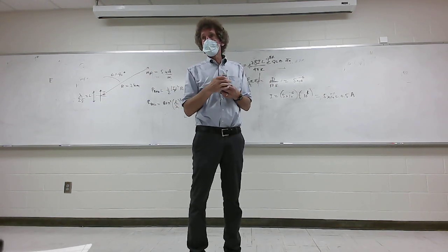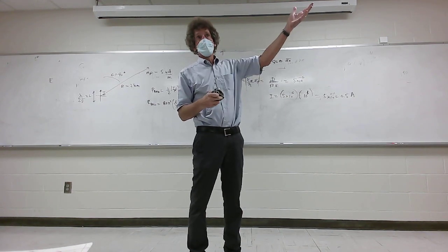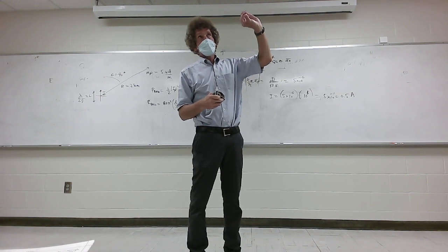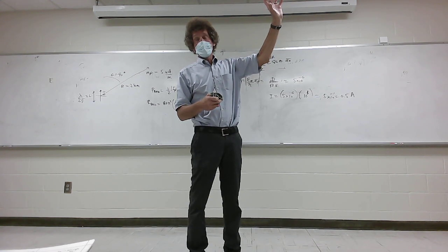Ideally, people would like power lines with 30 million volts with respect to ground and very little current. The problem is, you hit a point where the voltage is so high that it causes corona discharge around the high voltage lines, and then you get huge losses.